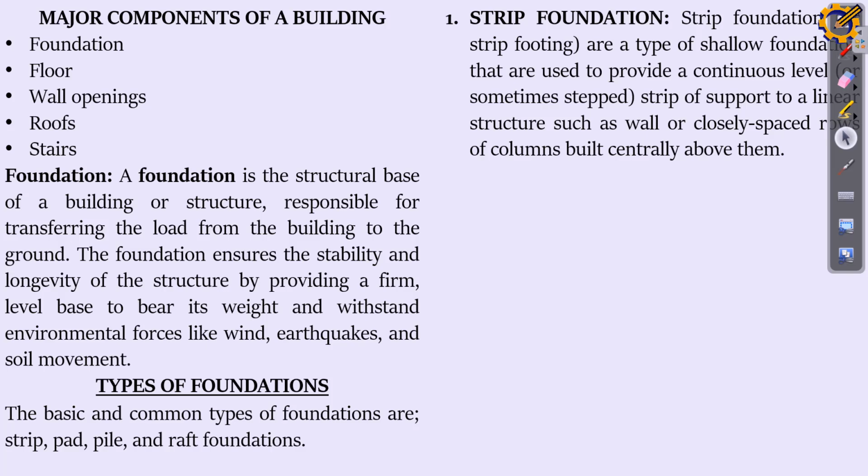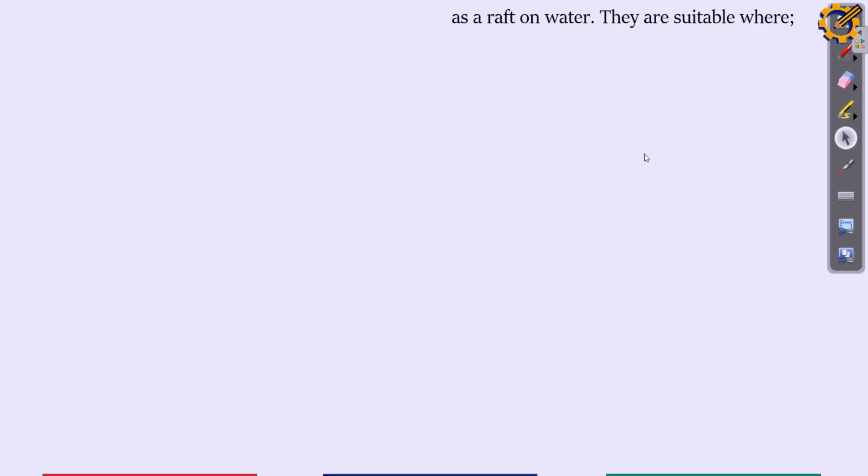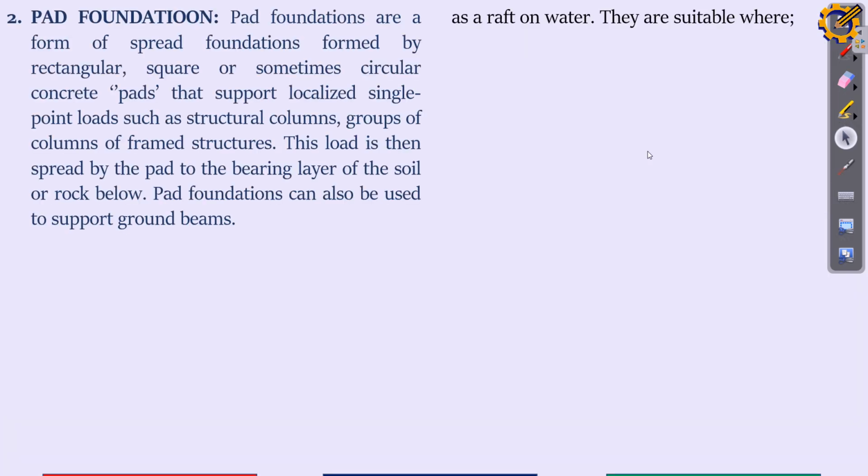Take the fence of your house. If the soil of the area you are staying in has a good bearing capacity, that is, it is not waterlogged, then the foundation used for the fence is a strip foundation. Okay, so take note of that. I don't need to read through; I will just send the material, and you can read it from there.